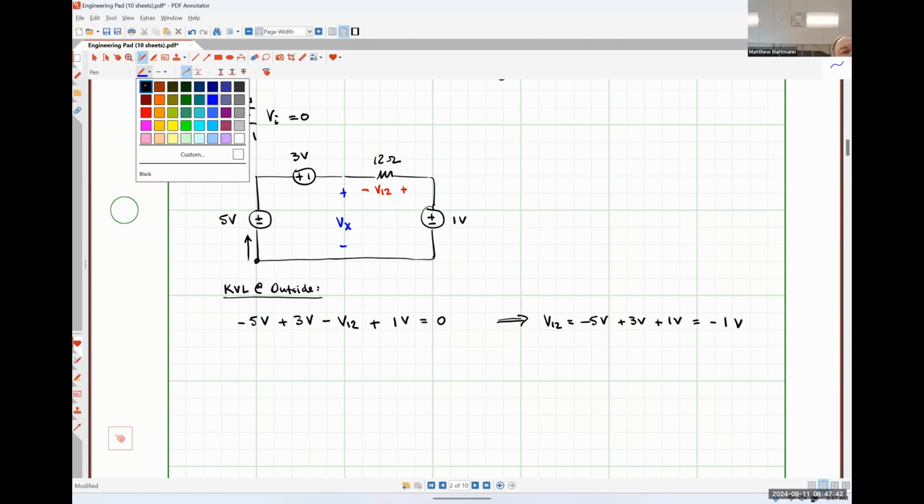So if I drew this open circuit, we would just be finding the voltage drop between these 2 points in this particular circuit, which is all a voltage is. Finding our voltage here using Kirchhoff's voltage law is effectively the exact same thing as just using a multimeter to find the voltage between 2 points in a circuit. We're just using other known quantities instead of a tool to do it for us.